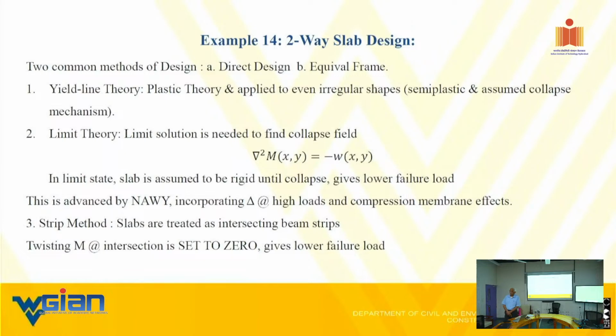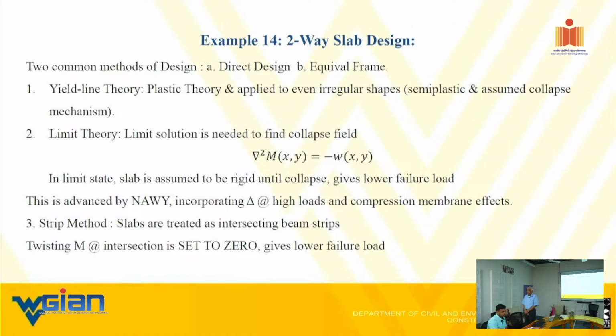I'm not asking about one year from now. If you test two different kinds of FRP reinforced members, and they are over reinforced, the final strength will depend only on the grade of the concrete, on the strength of the concrete and not that of the FRP. Correct. So how can we experimentally differentiate between those two members? So we make them under reinforced.